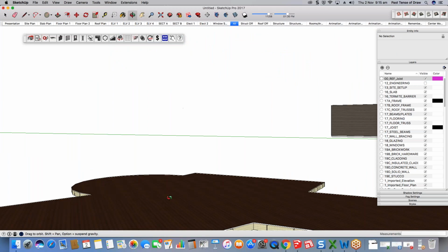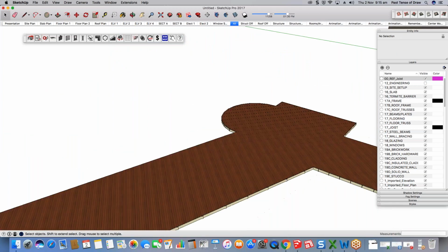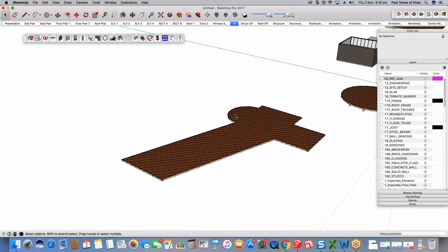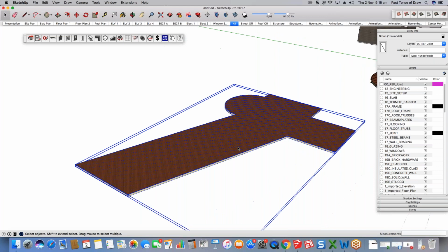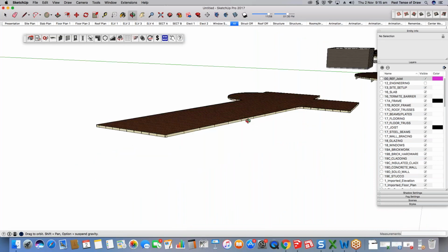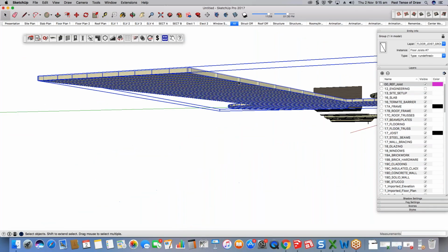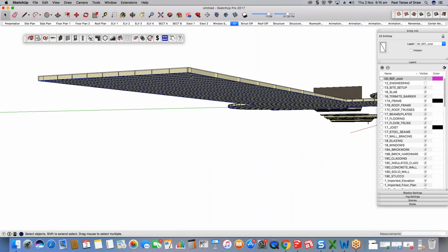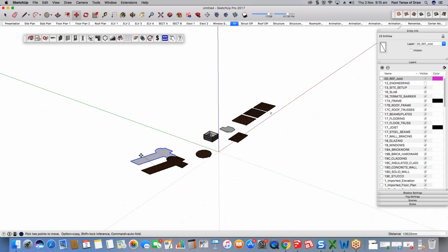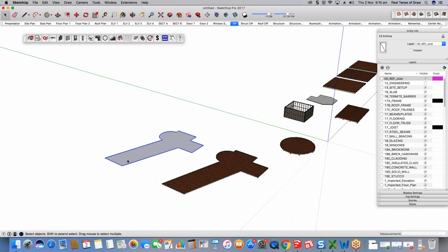Now, if you do groups, the actual joist tool is also going to be assigned to that group. So sometimes it can actually be good. I normally would suggest that you don't actually double click into the shape. You first explode the shape again. Okay, I'll explain that in a little bit more detail.